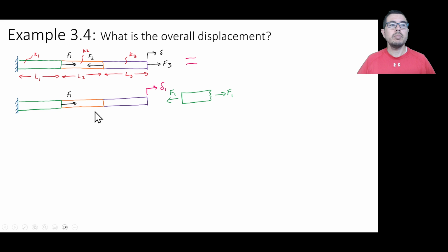What about what's happening on the right side? Well, on the right side, we have 0 applied force here, 0 applied force here, quite frankly. And if we do a section, so we cut this here and we keep the right side, this is 0 forces, maybe being applied at the end. So 0 force. The internal force is going to be 0 as well.